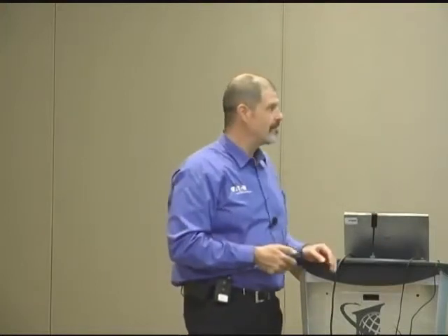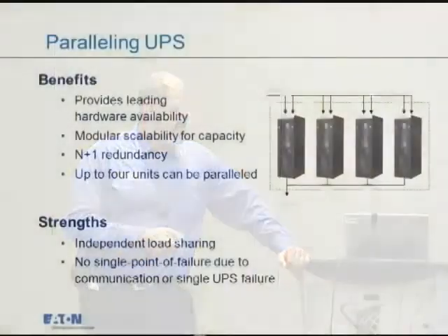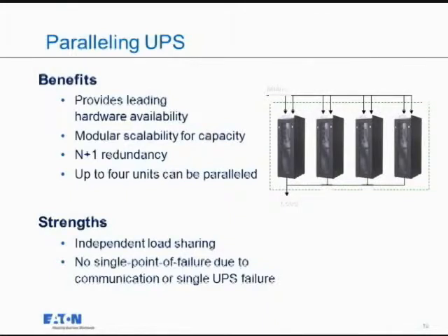Again, the concept remains the same. The size of the blocks differs from application to application, organization to organization, requirement to requirement. But it gives me that ability. The paralleling gives me the ability to scale out, and the ability to add redundancy if it's required. And again, the strengths here are independent load sharing, where they're not communicating, and elimination of the single points of failure.